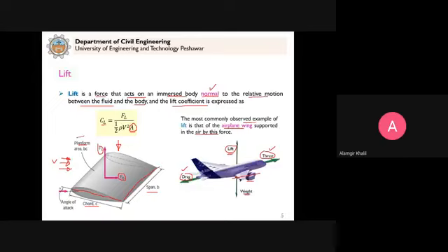So that's why this is the planform area, and it is given simply by b into c. Normally, remember, for this area, even in the case of drag forces, we just consider the projected area on a plane that is perpendicular to the force vector, either the drag force or the lift force. So this is the important characteristic area.